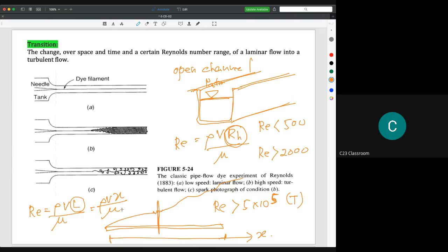Okay. And then if you read about the boundary layer, you will find that the surface roughness is actually an important parameter to determine the Reynolds number. In a smooth surface, for example glass, a very smooth surface, maybe your Reynolds number for the transition is 1 times 10 to the power of 6. We could consider that, so it's changing actually. After this, we will see more about the boundary layer. You will find that it depends on the experimental work, because it is not easy to determine it with only one single number.